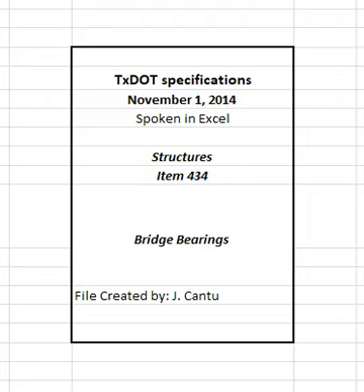Sliding elastomeric bearings. Consisting of a steel top sole plate with a stainless steel facing, upper component, bearing on a lower component. The lower component consists of a layer of polytetrafluoroethylene, PTFE, recessed and bonded to a steel plate that is vulcanized to the top of a laminated elastomeric bearing pad with or without special components, steel guide bars and